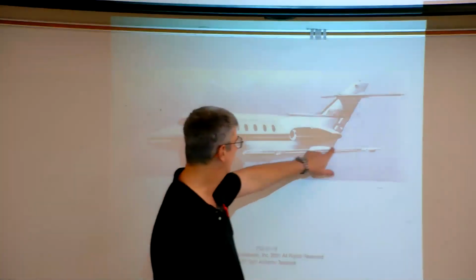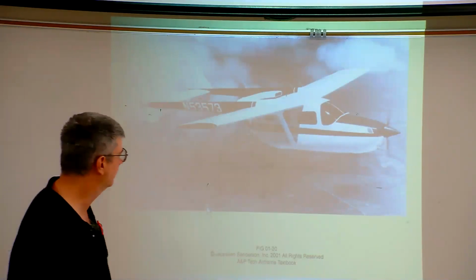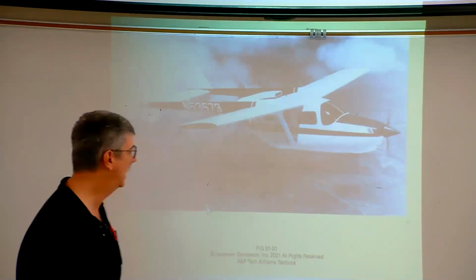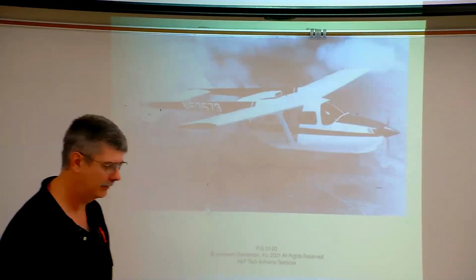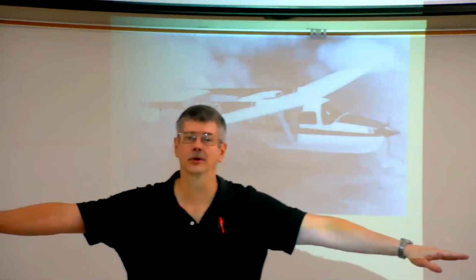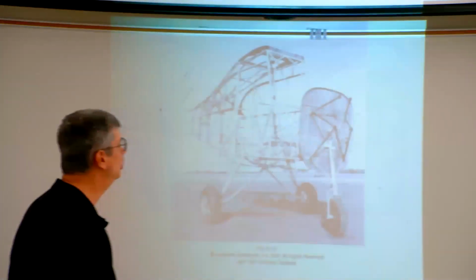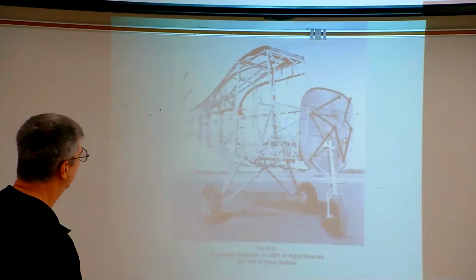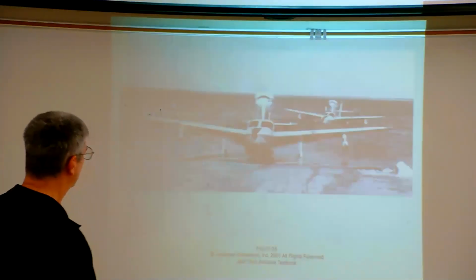Here again, we see a wing fence, but then we see the different positions of our horizontal stabilizers. Here we have a push-pull, or a Skymaster 337, with a centerline thrust. Mainly that was to help reduce the danger of asymmetrical thrust when a multi-engine aircraft was to lose an engine. Here we have a truss type structure, nothing special there, retractable landing gear.